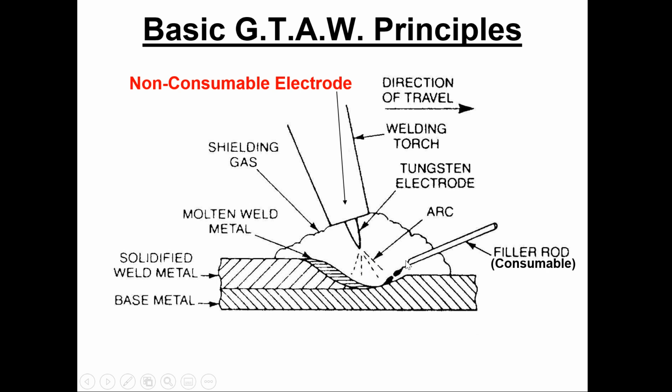And as long as we keep this inside protected, everything should be good. The tungsten itself, of course, is non-consumable, but it needs to be watched. And if you ever touch the filler material, even accidentally, to the tungsten, immediately stop and immediately change it. It will actually start causing a lot of problems to the metallurgy in your material because you've added this material to it, and it'll actually end up sticking there. So you need to redress and take it back. Big deal.